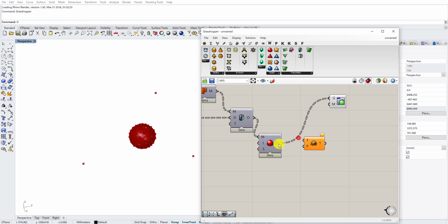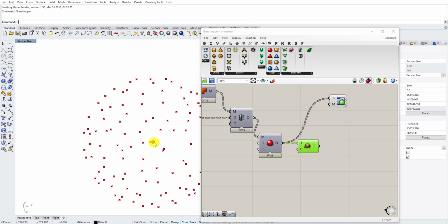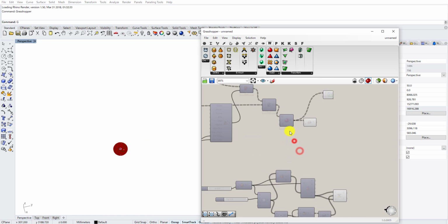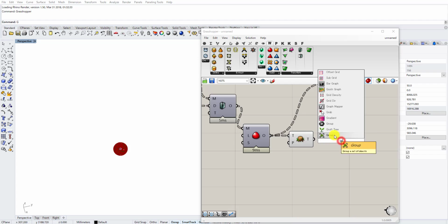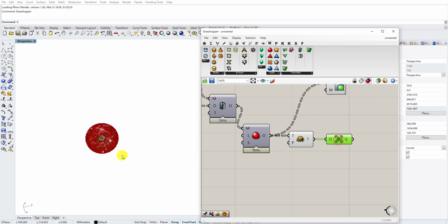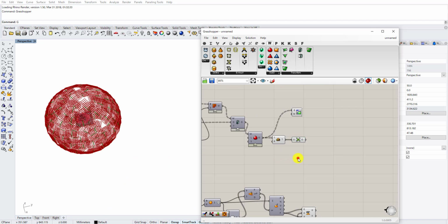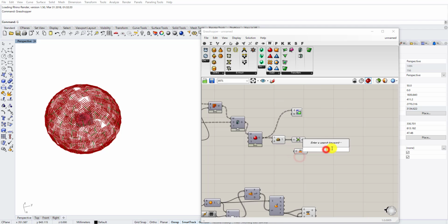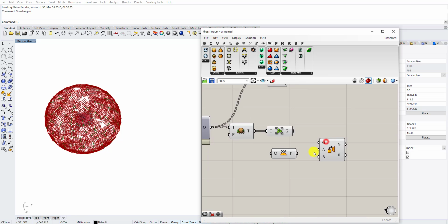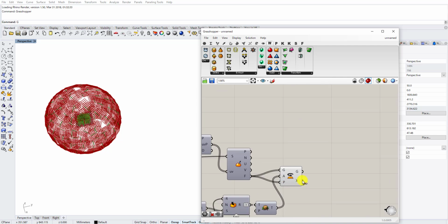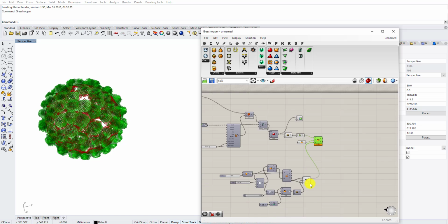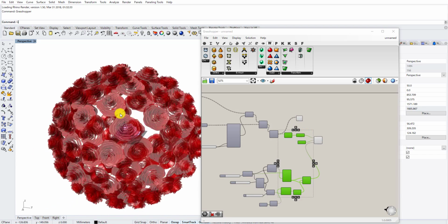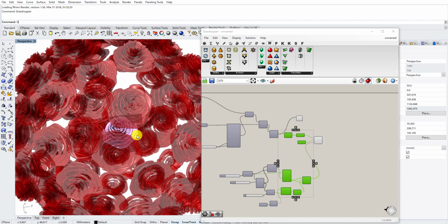let's first flatten these roses, base roses. What's this? And make a group. And since it's been made on 0, 0, 0, I could just use XY for a base plane and use the orient from XY to this here frame. Now that I got flowers placed on the sphere,